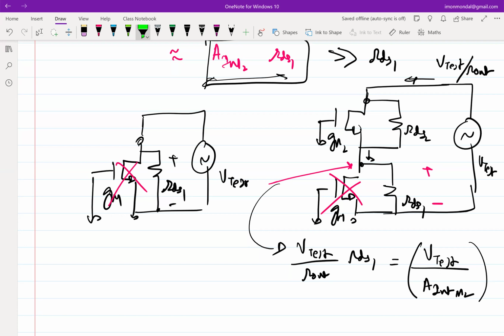Your question was, if I put up a circuit like this, it seems like the top transistor can go out of saturation. 100% it can, but the job of the designer is to ensure that it does not. The question is how I bias the circuit on the right, with the two transistors stacked on top of each other. That is the next thing, and you have already done that in some of the assignments. Before I come to that, any questions on this?